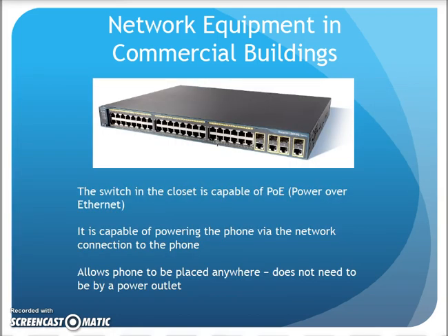Well, this switch port needs to be capable of what's called power over Ethernet. It'll actually give that phone power through the Ethernet connection, through the data wires. Keep it simple. It's going to provide DC power across the data wires to that phone. This allows the phone to be located anywhere in an office and it'll receive power. There's more reasons, but that's the simple one.